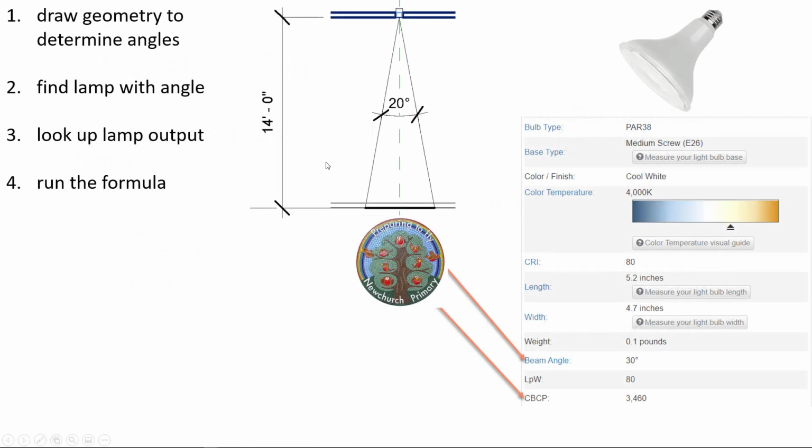Well, let's draw it up. Okay, that's really the start of a single point source calculation. Here's an example. You're trying to light a mural that's on a floor. You're trying to light it from a single spotlight, a single downlight above it in the ceiling, just a recessed can. But you know you're going to buy a special lamp to put into that can because you need a high degree of control of photometrics, because you want that to be really bright compared to the adjacent floor. Well, what you do first, you draw it up.